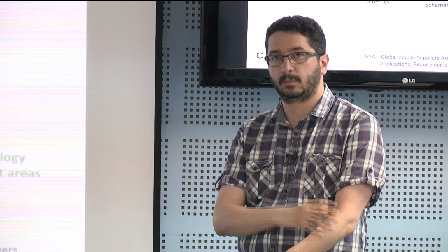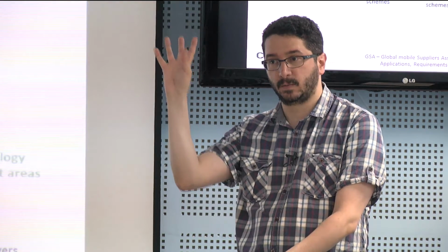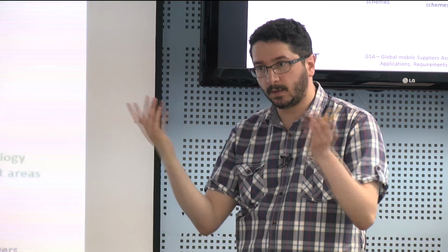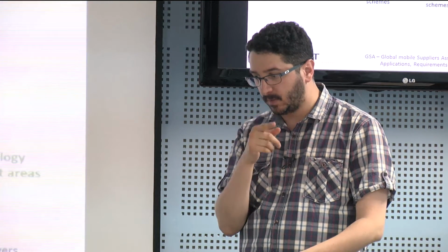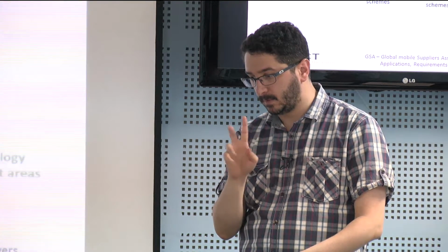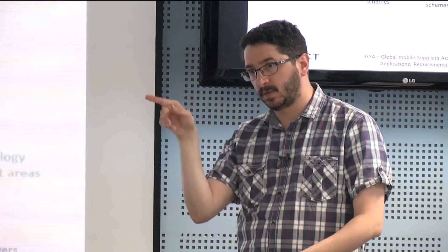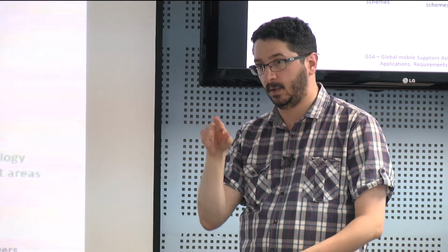basically you would add 10 times the logarithm base 10 of the number of antennas at the base station. So if you have a lot of antennas, say you have 100, what it means is that you have 10 times log 10 of 10 to the second, right? So it means 20 dB, okay, immediately.